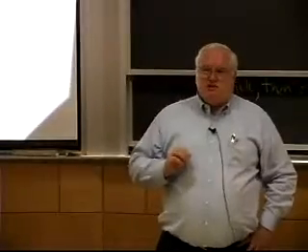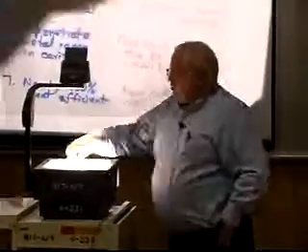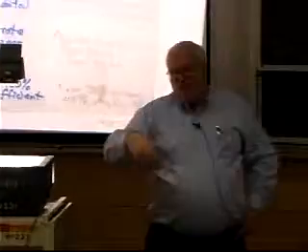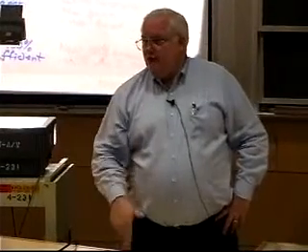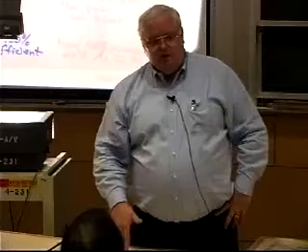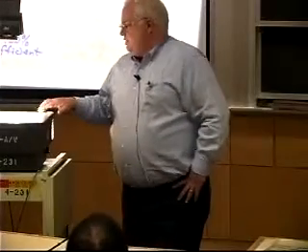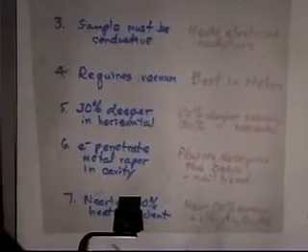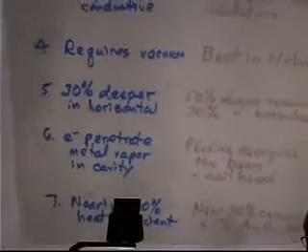and the reason they're best in helium, when you have this huge number of photons come shooting down through here, just above the surface, you got metal vaporization coming on. That's what's helping you. It's the reacting metal vapor coming out of the weld pool that's drilling the hole that gives you the deep penetration. It turns out that the metal vapors, if they get heated by the photons coming in, will give off electrons. Once you give off electrons, free electrons absorb laser light wonderfully.